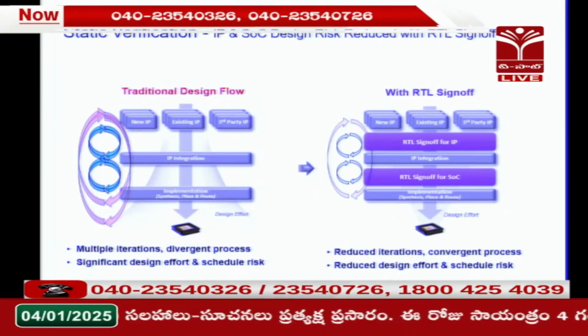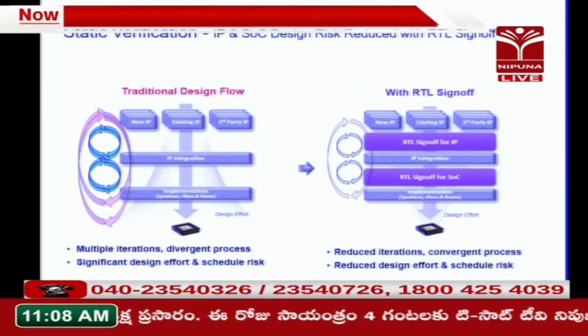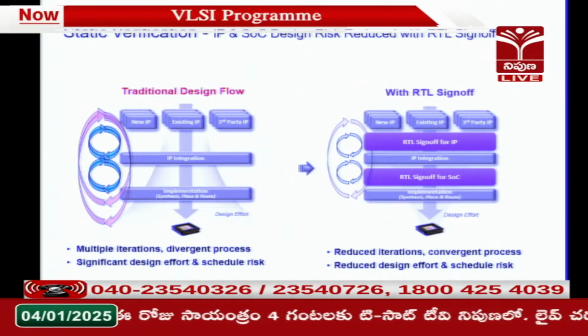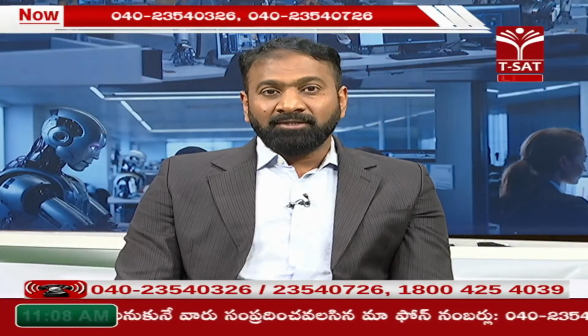So that's the advantage with static verification, which can help you to do what we call sign off. Sign off is where we say the RTL is good, RTL is clean. That's the sign off which you can achieve right up front during the early design phases itself, instead of going to the implementation. When the implementation has an issue, again you go back to the initial design. That is a time consuming process. But if I can catch such kind of implementation issues upfront during the RTL design, it can help to speed up my verification process, and it can help you to deliver that product to the end user in a faster way.